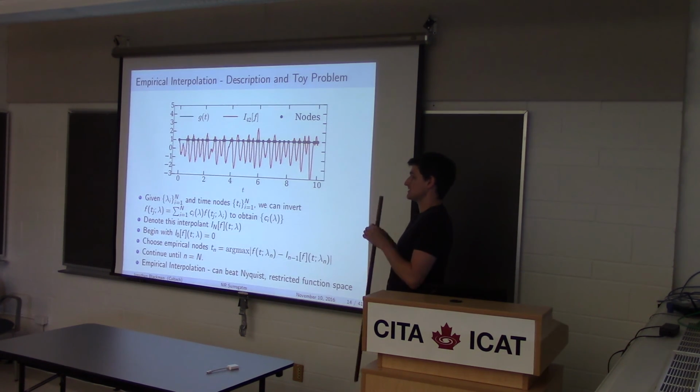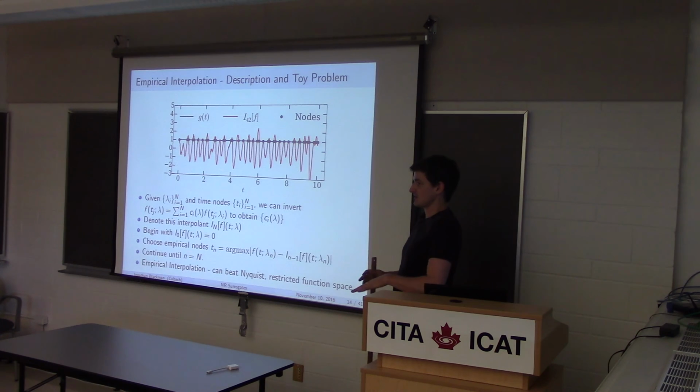So you need to know the value of the solution at the empirical nodes, and you multiply this with some pre-computed matrix of new basis vectors. And these new basis vectors are the empirical interpolant basis vectors, which are different from the orthonormal basis vectors you've constructed before, but they're a linear transformation of them. And you can compute them ahead of time? Yes. Yep.